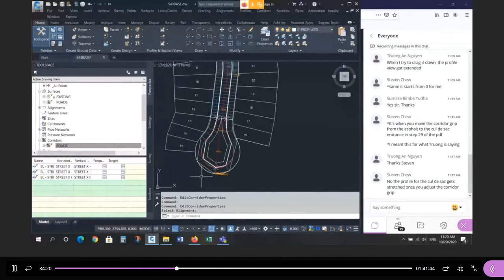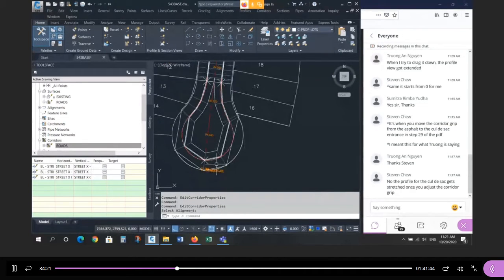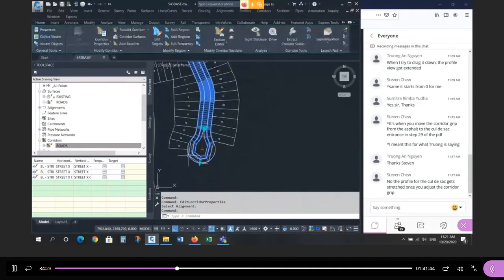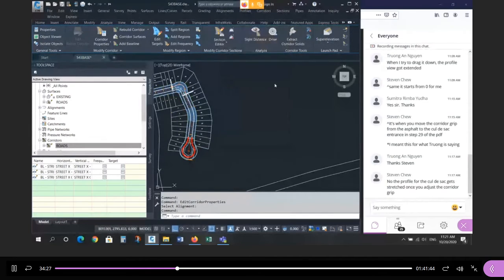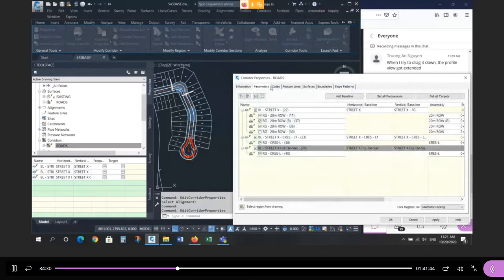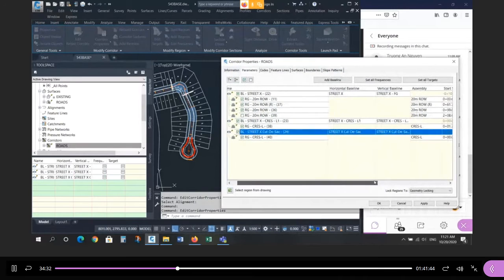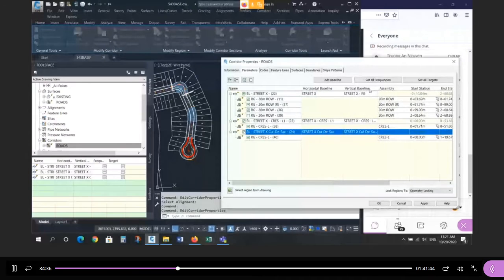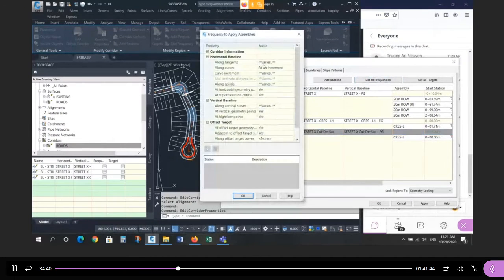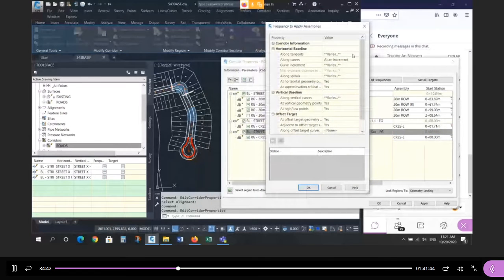So now it built it. It looks kind of funny, right? Doesn't look circular, no matter. Let's fix that. That's a frequency issue. So let's look at the frequency. So by default, the frequencies are all 25. So let's go into here. I'm going to set all the frequencies again, right? So they vary because by default they're all 25.